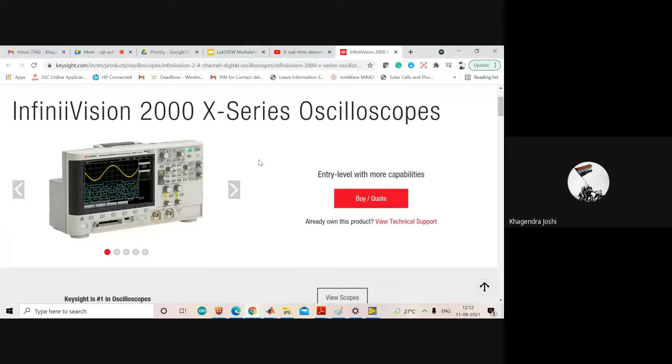So what all is visible on the screen? Can anybody tell, basically related to the DSO picture? A sine wave. A sine wave, so basically a front panel is there with a scope or a graphical representation of whatever we are feeding. In this picture, nothing has been fed, so we can consider it a saved waveform on the screen. Then it has some rotating knobs which you can see here, some push buttons, and some feeding points. These are the BNC connectors. Some USB ports are also there.